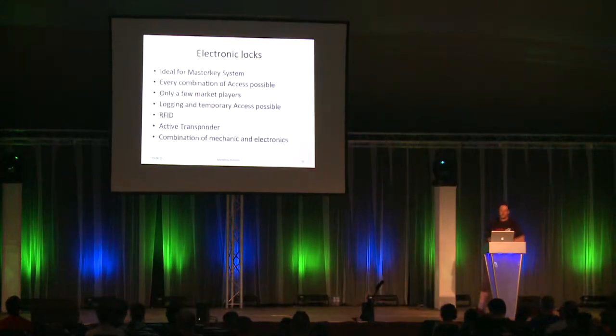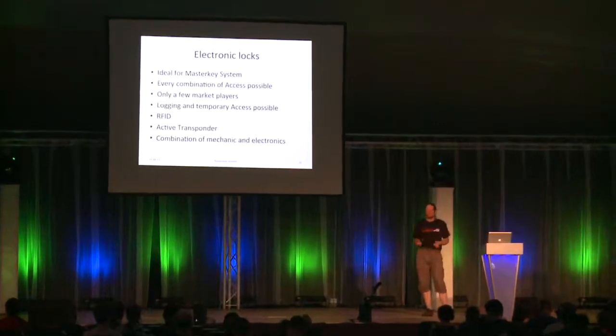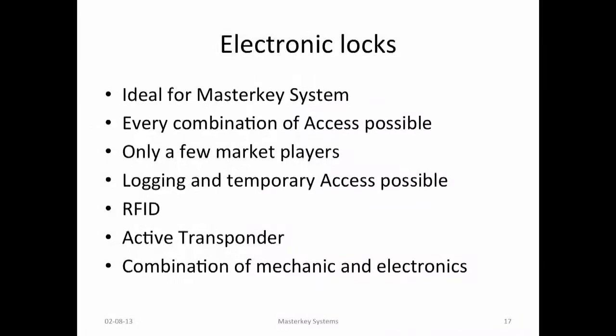So the difference, what other things is electronic locks. Electronic locks are the locks that fit in a standard door lock, not like card systems or something with an electric strike. I think it's a very common solution. You can make any access control you want. You can time access. You can give access for only different doors. You can give access to many doors. You can set a time on it, so it can only be entered during work times in this room.